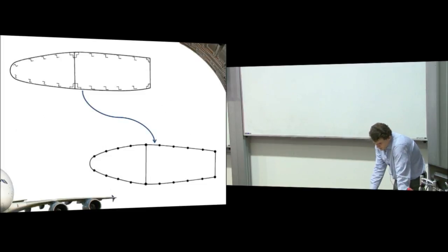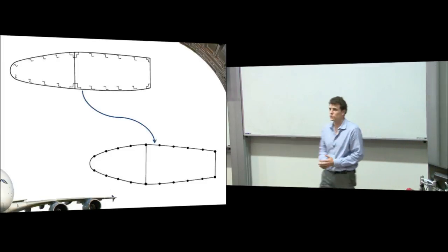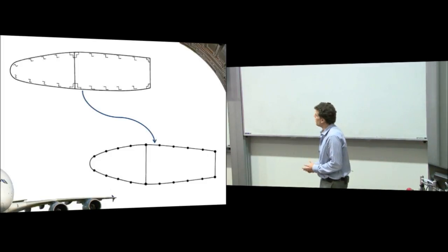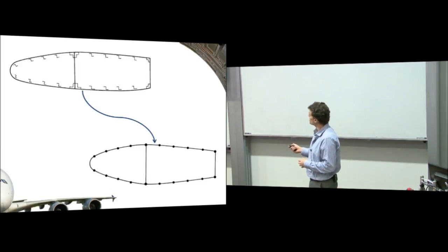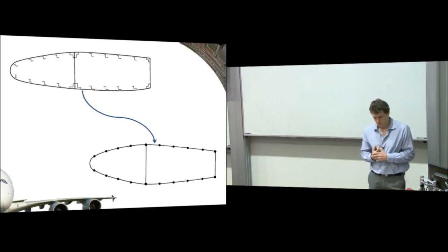The first is that we can take problems like this, where we have stringers and skin and all sorts of problems, and collapse them into booms and panels. And generally, when you see a 2D drawing like this, the booms are represented by little dots, and the panels are represented by little straight sections, just like skin.